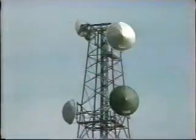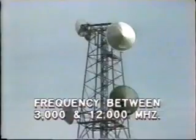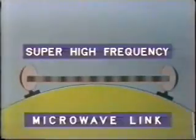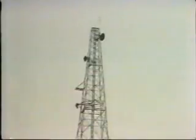Okay, let's now take a brief look at radio communication by microwave. In this system, the signal is carried at a much higher frequency, between 3,000 and 12,000 megahertz. This super high frequency signal, SHF, is transmitted by radio from terminal to terminal. At each terminal, a dish antenna is installed, and the transmission must be by line of sight. The super high frequency waves travel only in a straight line. They do not follow the curvature of the earth. Therefore, for long distances, many repeater terminals are required.